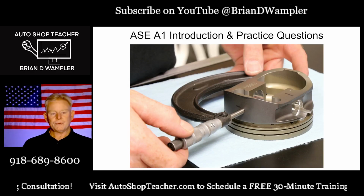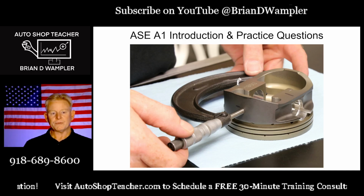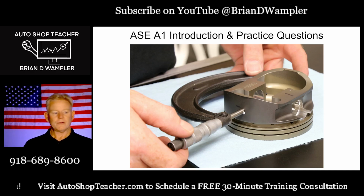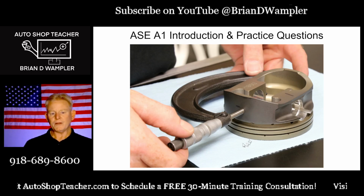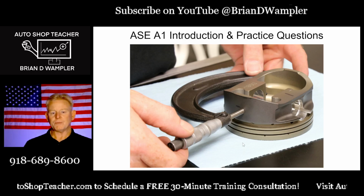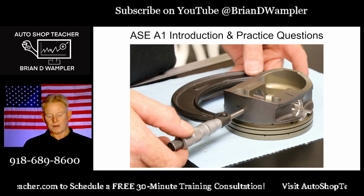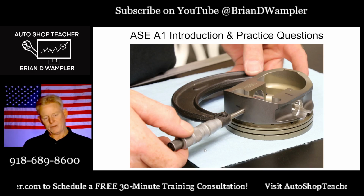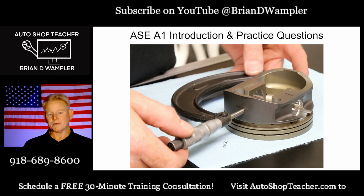Here is showing using a micrometer to measure in that area, that portion of the piston. Hopefully that gives you a little bit of an idea of why you would measure there. But I want to point out something from this stock image photo. This technician is not using this micrometer correctly.